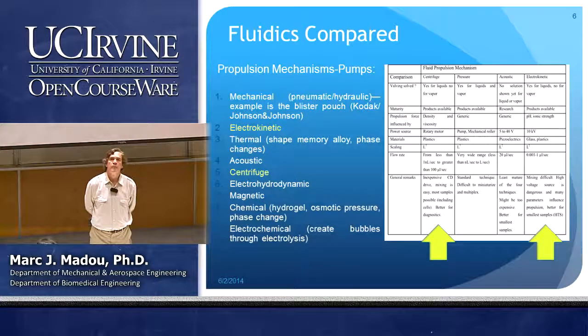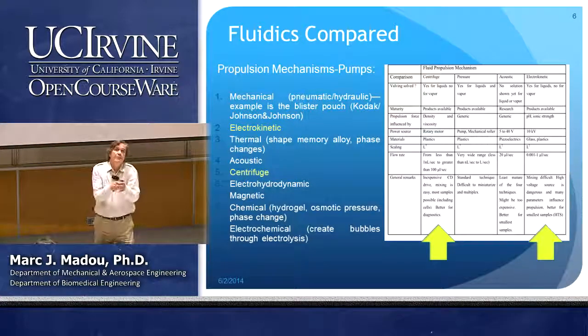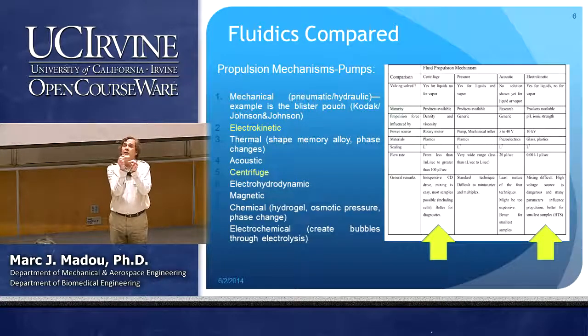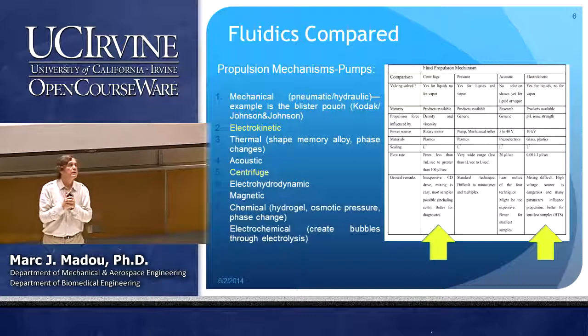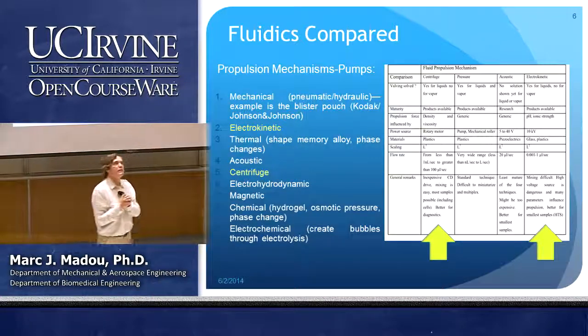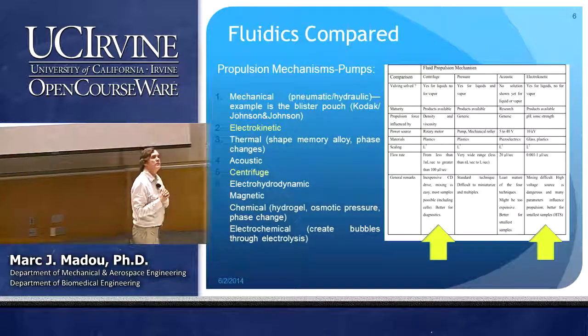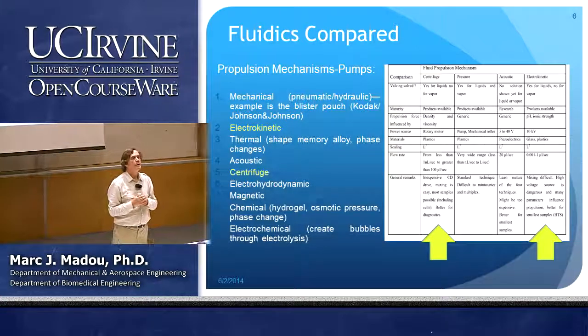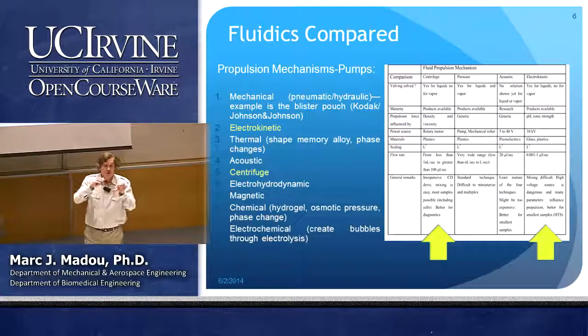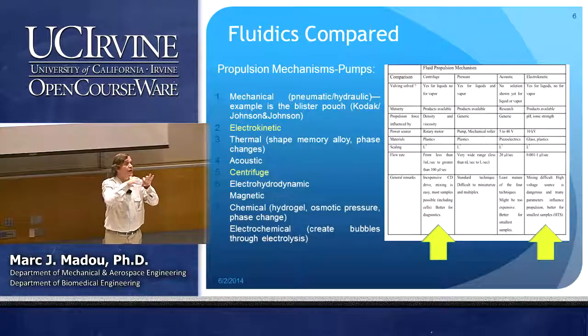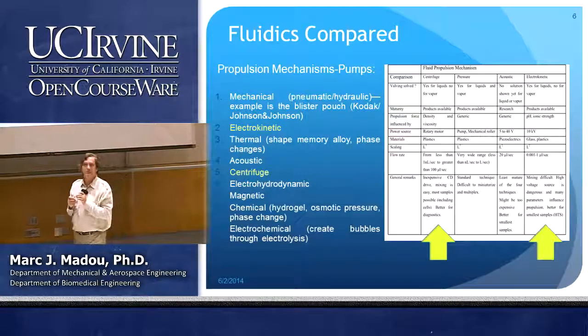Yes? Can you pressurize it with something like an inert gas? That still would have the same problem, right? Because the diffusion of the water vapor would still go against that pressure gradient. That wouldn't help, no. There are actually some simple techniques you might come up with. Yes? Use some sort of hydrophobic material? No. Also, that would not work, right? Because the vapor can still go over that hydrophobic material. Be creative. What else could you do?